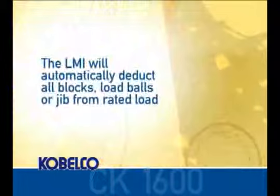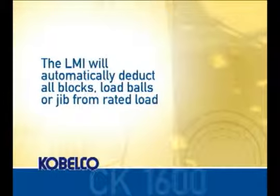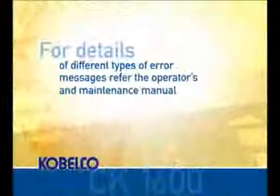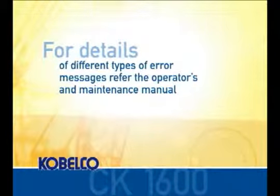As an aid to the operator, the LMI will automatically deduct all blocks, load balls, or jib from rated load. The radius is the distance from the center rotation of the crane out to the load block. This is the warning display bar. It will give the operator a visual message if one of the alarms is sounding, or will flash an error code if there is a problem with the LMI. For details of different types of error messages, refer to the Operators and Maintenance Manual.